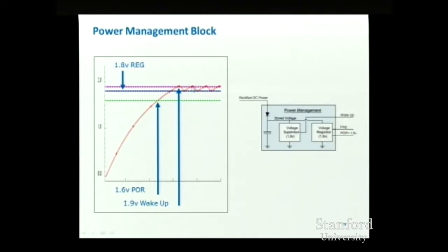Now, if the tag were further from the reader, there'd be less RF energy coming in, so this upward slope would become shallower, and it would take longer to get back to the charged up state. Because the tag is obeying the RFID protocol, it's going to spend energy at basically the same rate, so the downward slopes are always going to be about the same.